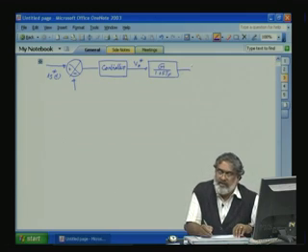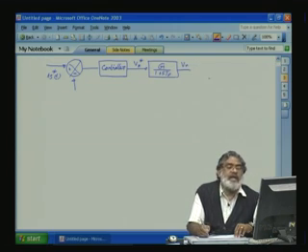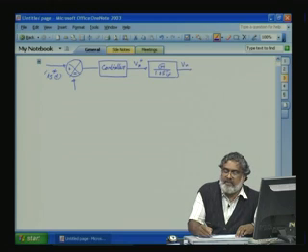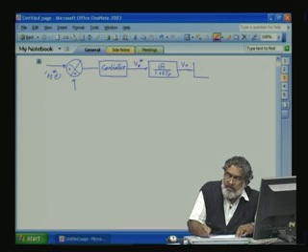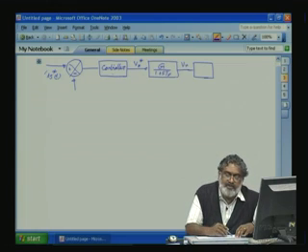Then here, this minus, this is the actual VR minus the source voltage, and the integral of this difference gives the current. But the controller we are trying to control has IST star as the input, so the source voltage we will assume as a disturbance input and will not take it in this control loop. Because we are going to design our controller with respect to any variation in our reference IST star.